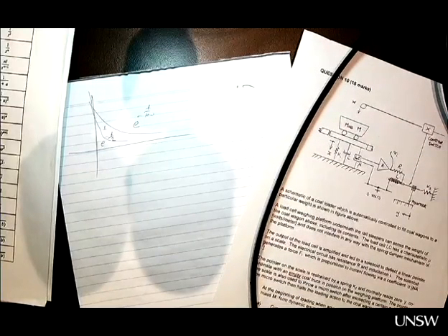So I just want to ask about the s-plane. I just realized that if the roots cross over this way, the damping ratio will be negative. At this point, the damping ratio will be 0. But along this way, the damping ratio will be greater than 1. This point here is a very tricky point, the neutral state. It's not just neutral stability, it's also the origin. Over here, the damping ratio will be less than -1.